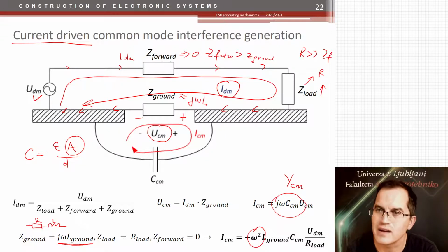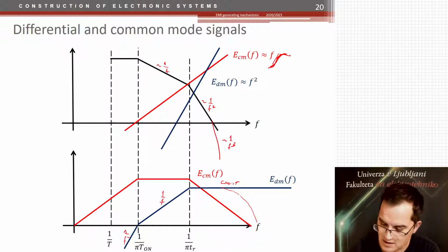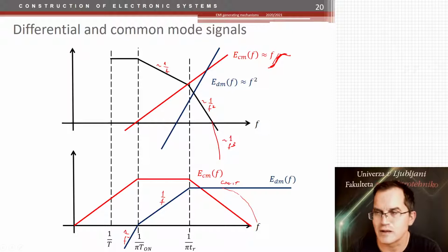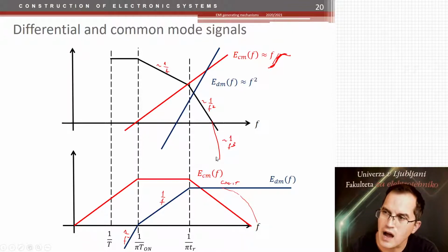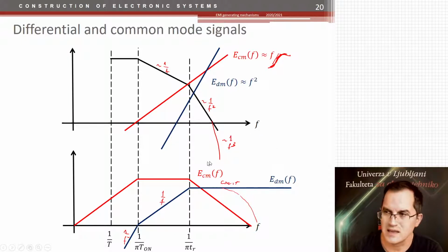Now, going back to the case which I was just telling you, even though the common mode noise here is decreasing with frequency at high frequencies, if we take into account the spectrum of the digital signal, the amount of that spectrum is more or less flat, so it will actually go upwards. But in the real case, it is again frequency limited.